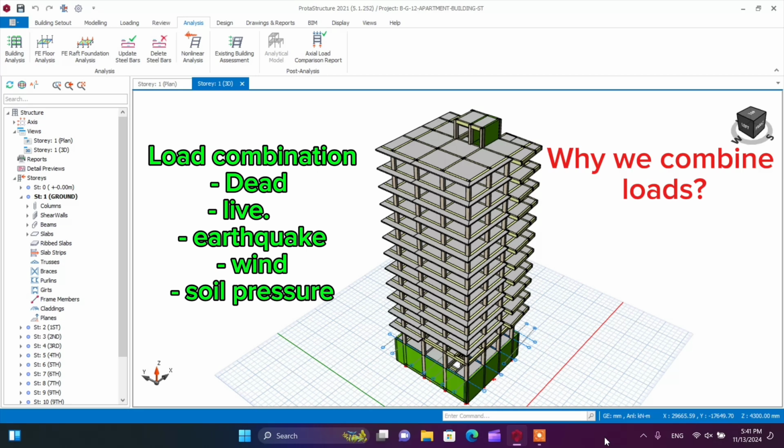Why are we going to combine loads, or what is the benefit of combining loads before we analyze or design the building? We combine loads to expose the building to all the real loads that may act on it, such as live load, dead load, and lateral loads such as earthquake load, wind load, or lateral earth pressure, and to make it withstand such loads.